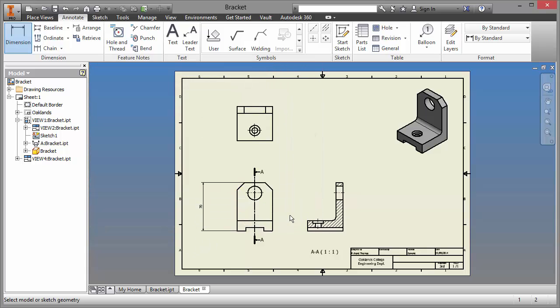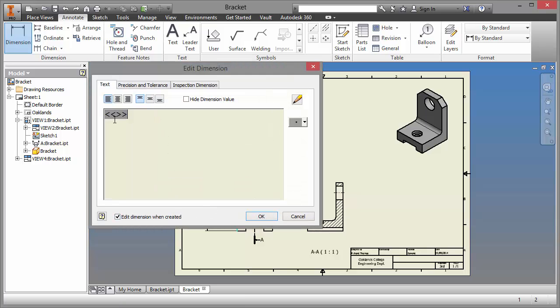So what I did there, if I just cancel out again, started the command, the first point, now I can either pick the end point or the actual line. Second click was up here, and then I put the dimension down with a third click. I then get this box up. I don't need to see this one every time because these lines are the note for automatic dimensioning, and we're just going to untick that box, hit OK.